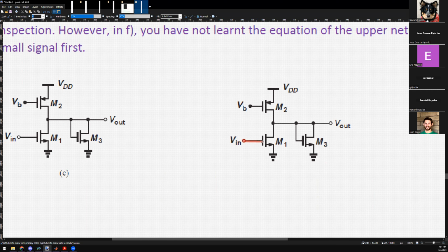It goes towards the drain of M2. Which way? Don't say up or down, tell me the node. Drain. Oh, source. No, the drain is the lower potential, and the source has to be the higher potential. So that's the source, and this is the drain. So after the drain, I hop up, and am I at the output? Yes, that way. Good. So we're home free.